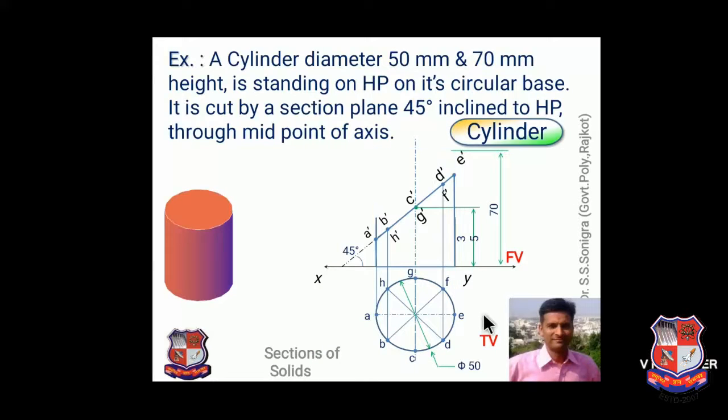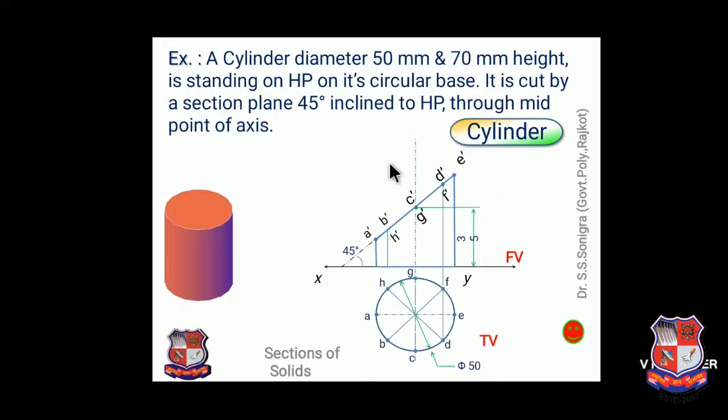Now how to draw the cutting plane or true shape of this section. So this is a removed portion. Draw it very light. No need to erase it completely; you can make it lighter. Now what should we do? Take projections from this point, meaning a line perpendicular to this cutting plane line from point A dash. Draw a line like this. This angle is 90 degrees.